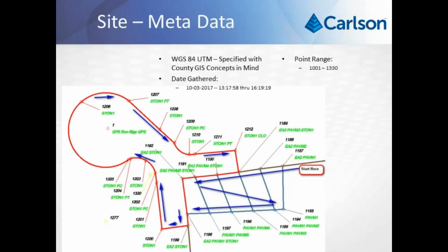So as I was coming into the site, this is the area where the GPS marker was stationed, my base station, and also where I have a lot of the parking lot areas, parking islands, and some of the building structures and sidewalks and things like that. And I decided to collect this up with UTM coordinates.